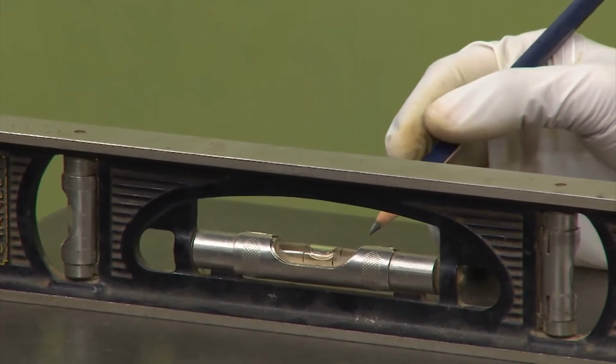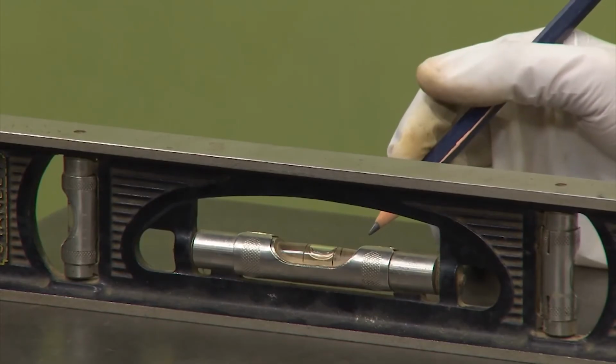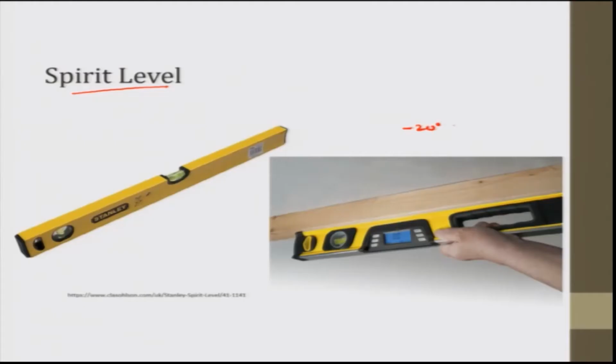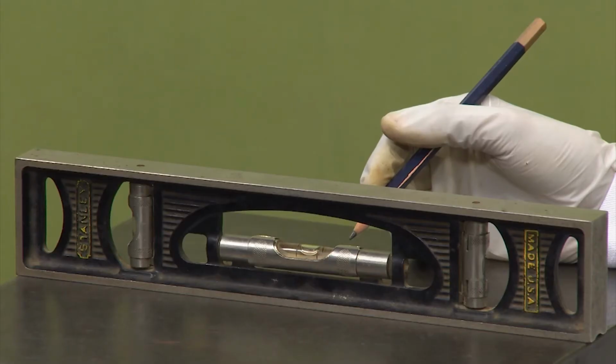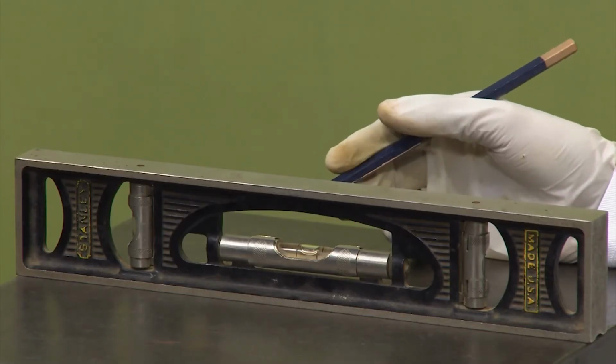This spirit level is sensitive to the temperature. The working range is from -20 degrees to 60 degrees centigrade. Actually, this fluid is also known as spirit. That is why it is known as spirit level. It is colored, and also a luminescent reflector is kept behind the vial so that the observer can clearly see it, as it illuminates.